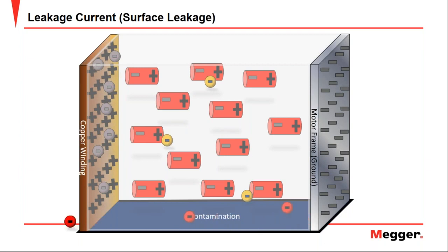And finally, we have the leakage current. This current is the one that circulates through the contamination of the insulation and increases as the insulation is more degraded or aged. At the end of the day, this is the current that we are interested in measuring in order to calculate the insulation resistance, since this current is indicative of the insulation system condition.